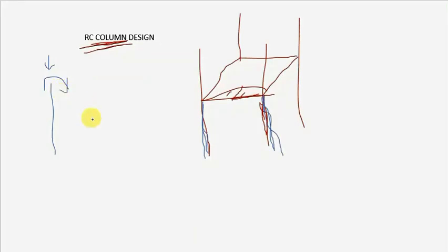It defines a strut as a member which is only subjected to axial stresses. That is for steel design. For this case, we just want to focus on concrete design, and so we're just going to handle our column as a member which transfers both the axial and also the bending stresses.